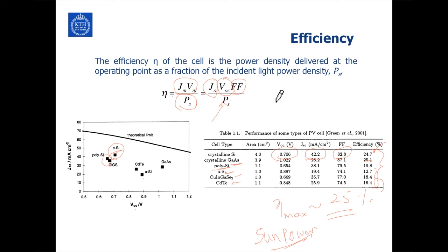So essentially what we have done in this section is we talked about the IV curve for a solar cell, and then how that changes with the intensity of the radiation, and then we defined important quantities: the open circuit voltage and the short circuit current density. Excuse me, this is J sub SC, you have to write, and that is V sub OC.